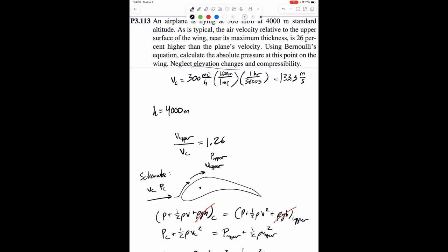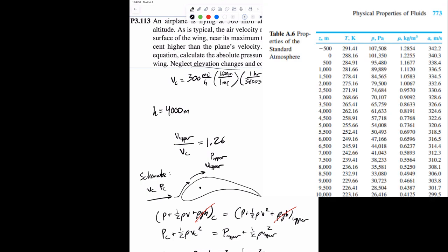Let's move to this next given variable. We're given altitude. In the recording, I'll show it to you guys, but essentially there is a table that correlates your altitude in the atmosphere to pressure, density, temperature, viscosity, those values that are important to fluid mechanics. Based on the equation from Bernoulli's, we just care about pressure and density.